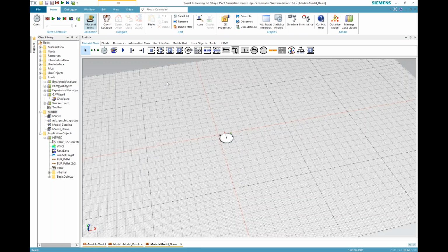With maybe just a half an hour for a very simple line, or maybe up to a few hours as you start to add complexity to your line, depending on what granularity level you need to get out of your model. So we'll just start at the beginning here, and I'll just model a very simple line. So the first thing I'm going to do is add a source for our parts. Think of this as your material parts delivery, or it could be a warehouse, it could be a supplier or a paint line or anything like that that's supplying parts to your manufacturing process.